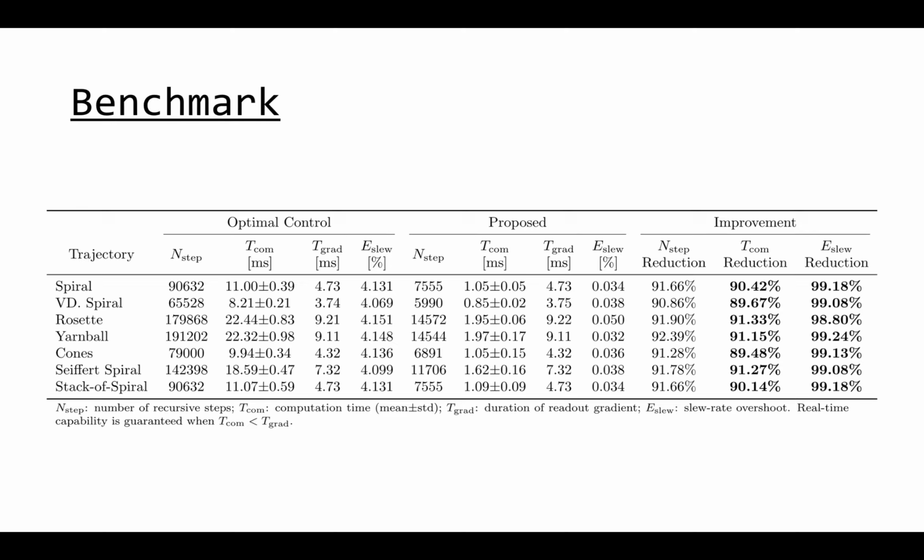And to derive the time parameterized gradient waveform, an interpolation is needed. This basically leads to a drawback that the sampling density of the arc length domain must be much higher than that of the time domain to guarantee the interpolation accuracy. In contrast, our time uniform method is hardware intrinsic and does not need an interpolation. This difference basically leads to the orders of magnitude advancement in our method.